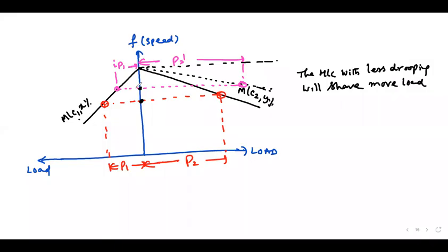Earlier, both are operating at 1500 RPM. When the prime mover input increases, it becomes 1600 RPM. But the synchronizing power comes into the picture and it is decelerated. It becomes 1550. Speed is reduced compared with 1600; it won't increase proportionally to whatever you have given.